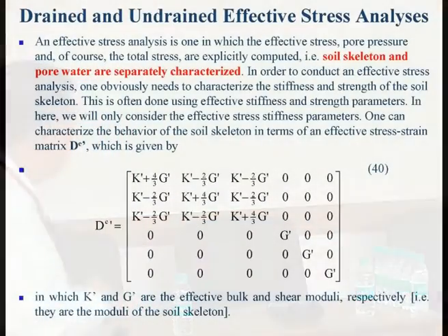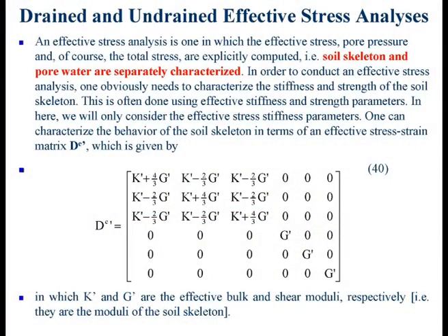I think there are other programs that also use total stress analysis. Then on the other hand, you can run using effective Young's modulus and effective Poisson ratio, which is not necessarily 0.49, maybe 0.2, 0.3, 0.35, that kind of thing. And yet, you can still get answers that are reasonable. And so, the question is, what is the difference between these two approaches? Okay? So, I hope to be able to cast a bit of light on that.